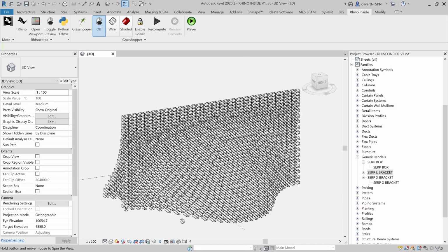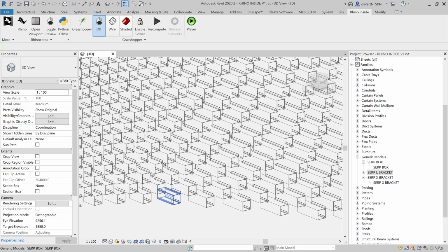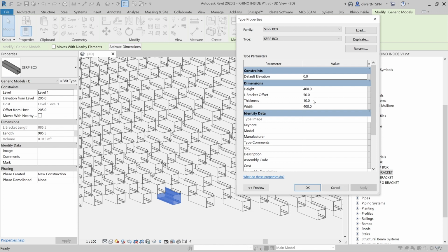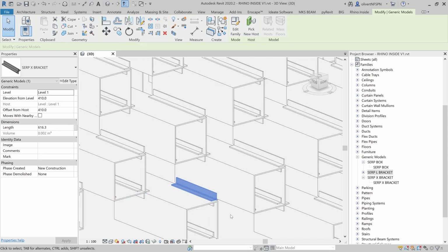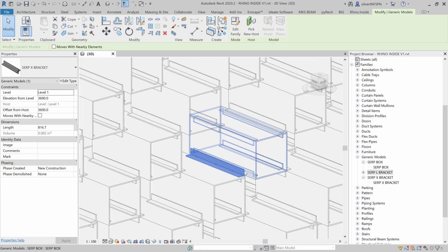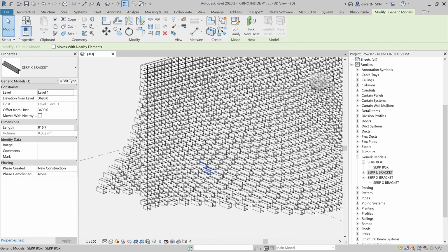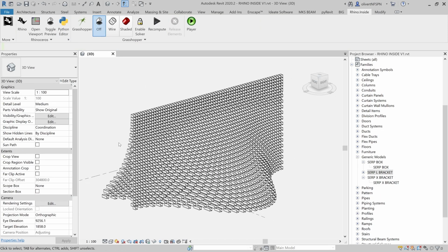And there we go. So this is how we can use Grasshopper to create Revit components. And of course, the beauty of this is, throughout the project, let's say the thickness of the box goes from 10 to 20 millimeters or something like that, I can still control this, so I still have a level of control, and I can add detail as well. So maybe I work out that there's a screw and a nut and bolt that goes in a certain distance. I can go and add that in. So this is the best way to bring stuff in if you want to continue working in Revit.